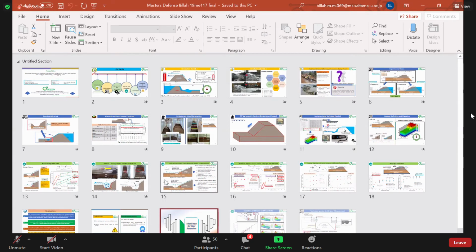If we place the hard layer on the surface, I feel that depending on tailwater depth, the headcut migration will be affected. In that case, I feel the tailwater depth will be reduced, so the migration speed will maybe be faster. It depends on the tailwater depth, yes. More tailwater depth causes more energy dissipation. So in the case of zero, the foundation level is in position, so I feel the migration speed will be faster.